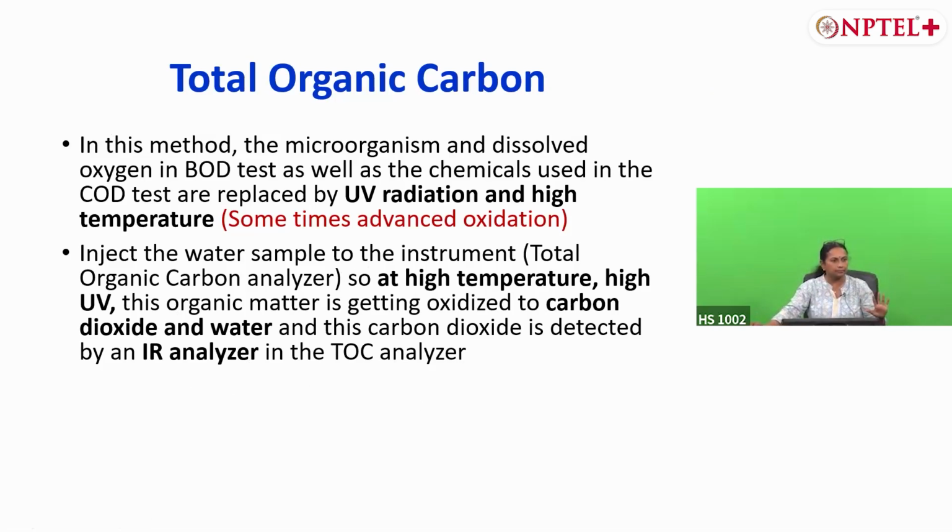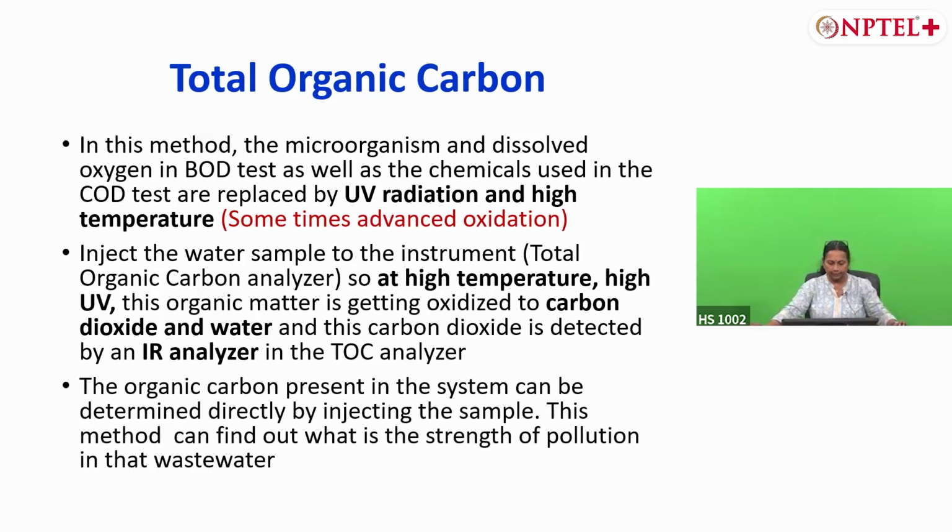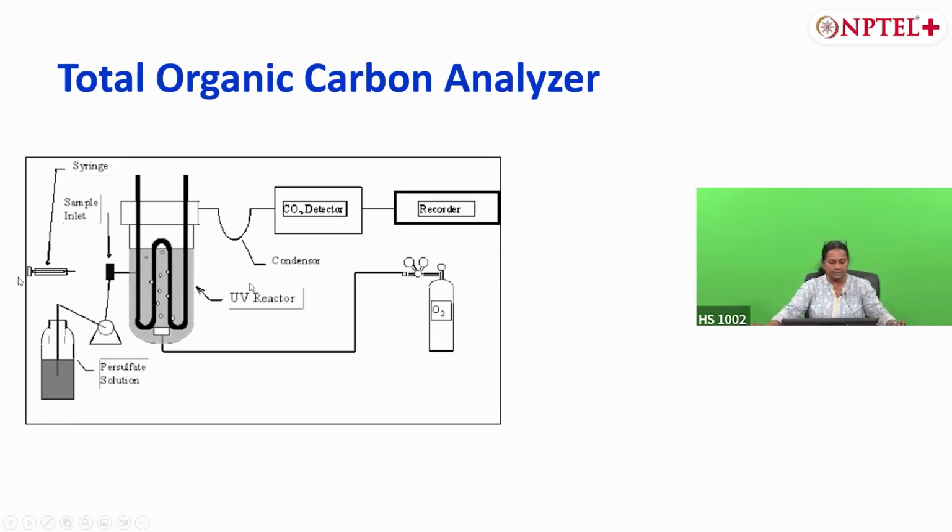Clear? For example, you have pharmaceuticals, personal care products and so on. Many times, even the COD test may not be oxidizing everything. So in such cases, if you want to see whether something is present in the system, this TOC analysis will help you.